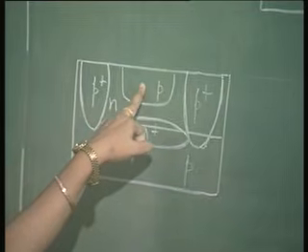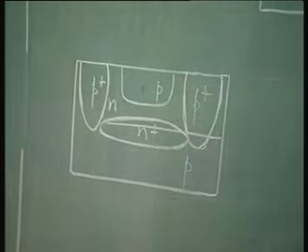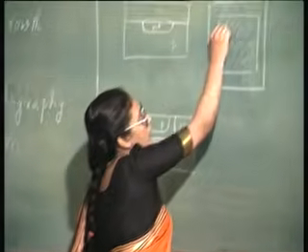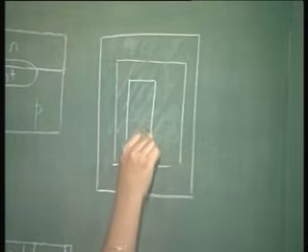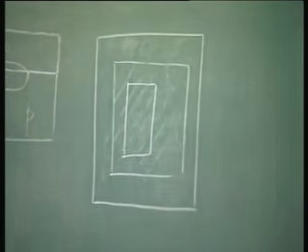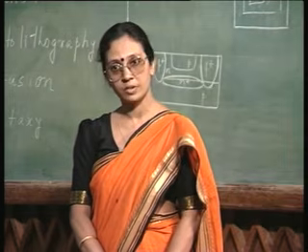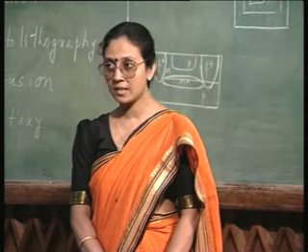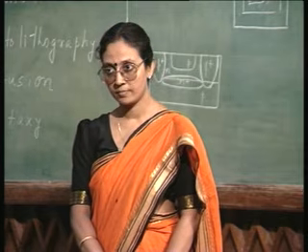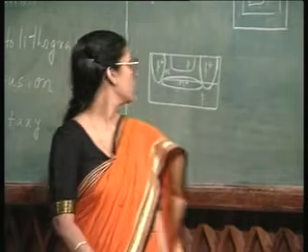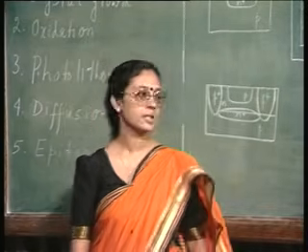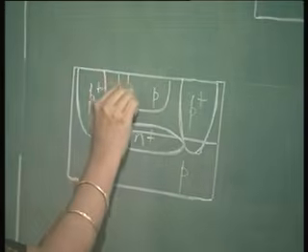Notice that this base P region is located within the active region mask, right. So, if you look at the top view, then your base is actually located within the active region mask. Only that portion is transparent when you are going to have the mask for the base. Its relative position is that it is within the active region mask. Okay. So, I have realized the base. Next, what do I want to realize? I want to realize the emitter. So, the emitter is here.